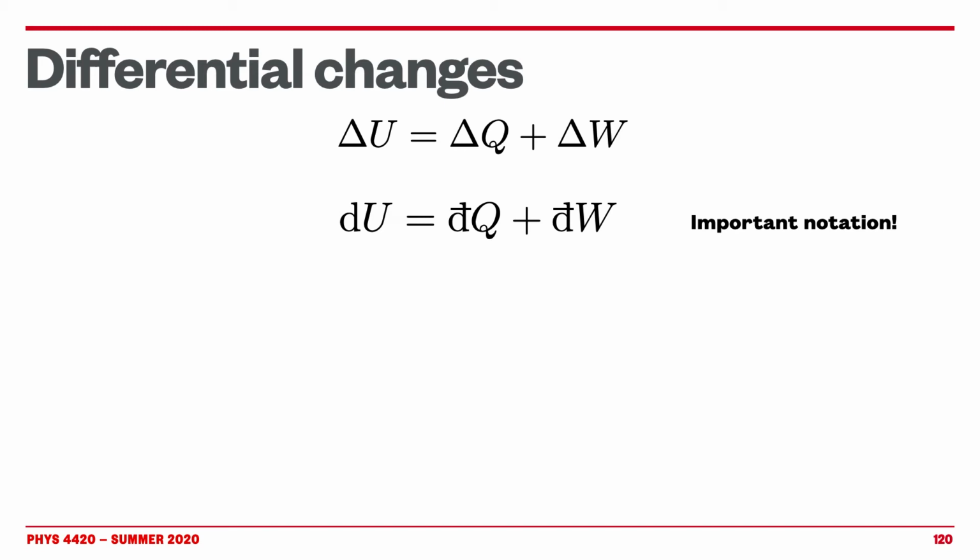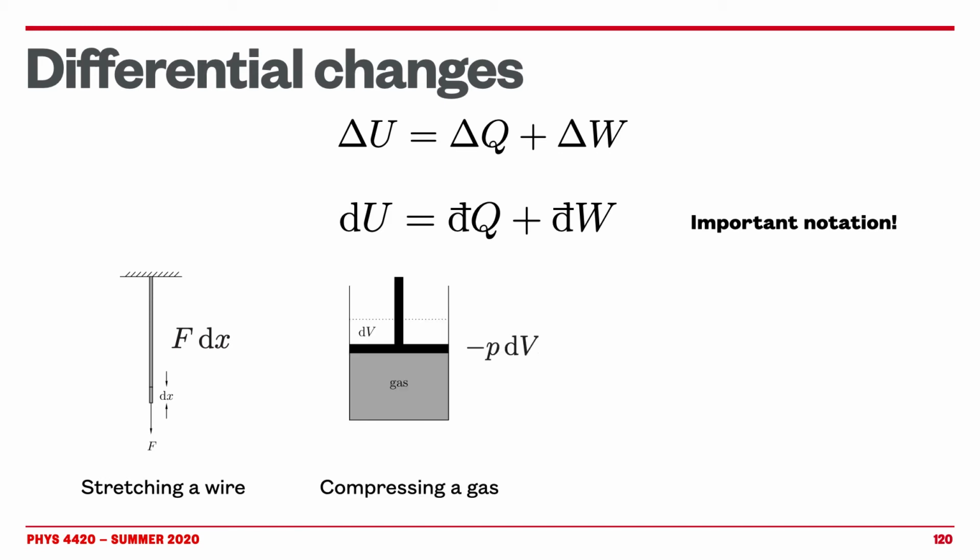Okay, so we can ask ourselves, how can work be done, or how can we do work? And the typical thing for work that we use in thermodynamics, even though there are a number of them, but we are going to focus on one in particular, is basically work is a force times a displacement, right? In principle, it's a dot product between the force vector and the displacement vector. So in one dimension, this is the force, for example, along x times dx. So if the system here is a wire, we know that the work done on the wire is f dx.